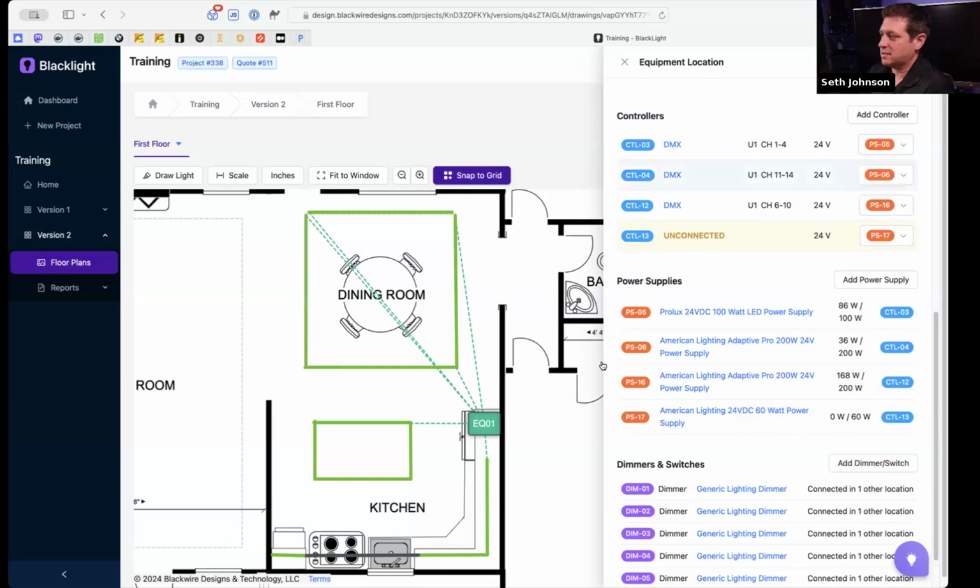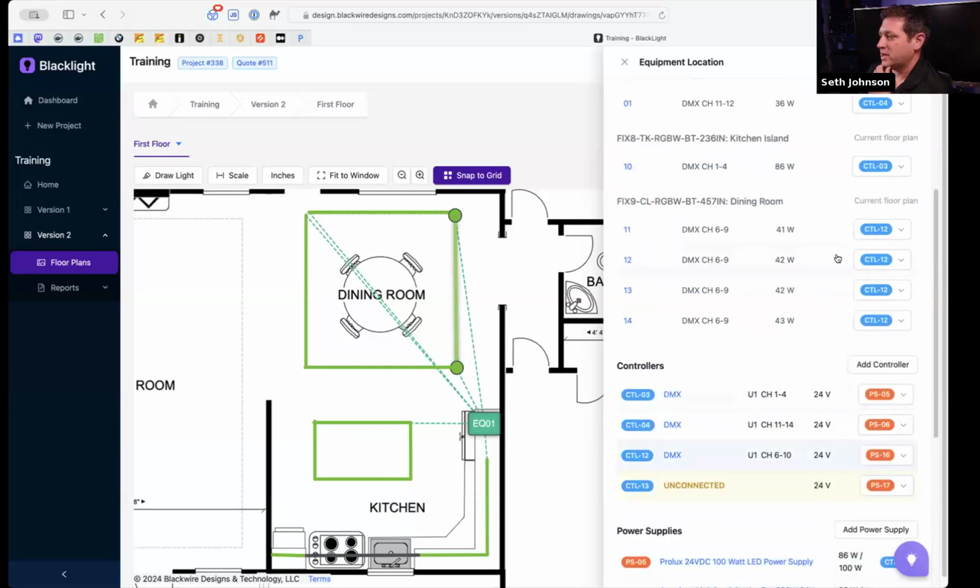Put that back. All right. It's still going to mess you up on class 2 power supplies. We will have another warning in the very near future on that. Basically what you would do here is you'd have to split this particular fixture up into 2 different DMX controllers to keep everything under that 96 watts. But we already have another controller here, so why not? Let's do it.